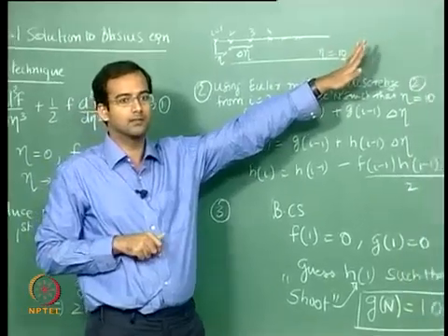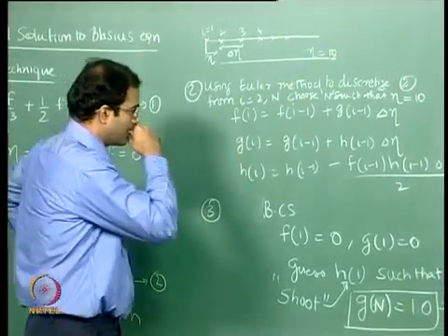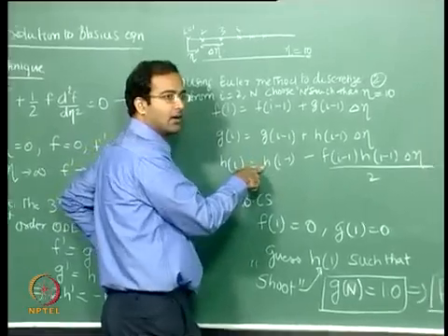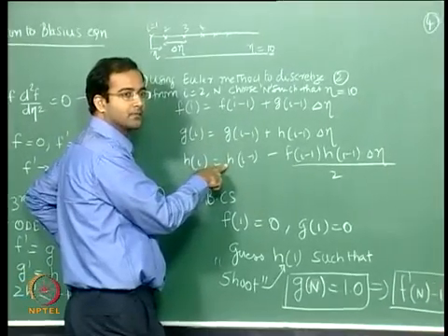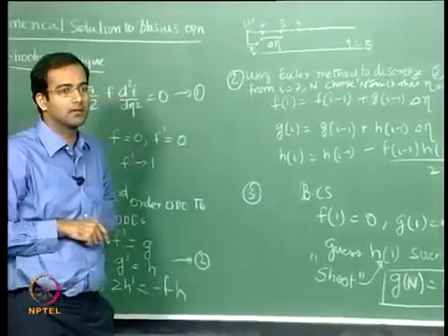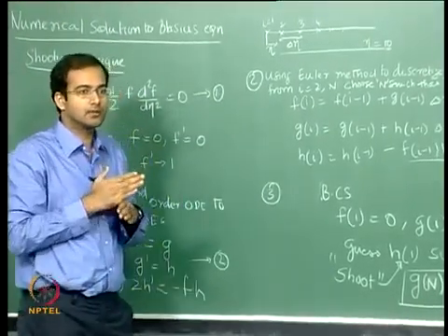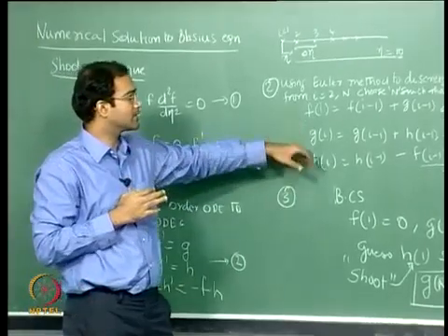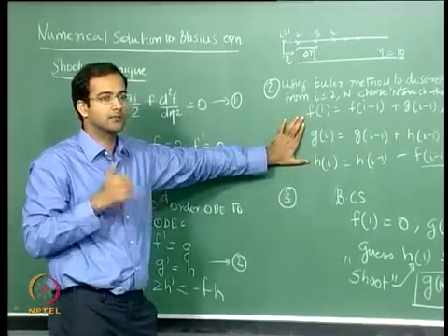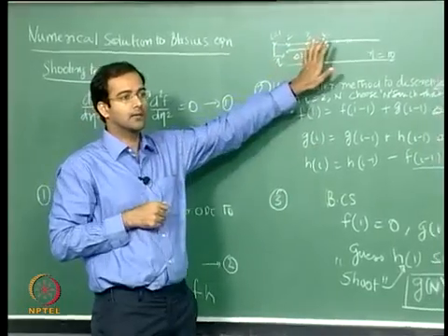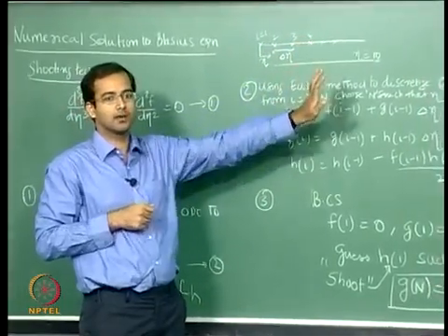Now for this you need boundary conditions for f, g and h all at i equal to 1, which corresponds to eta equal to 0. You need all 3 values at eta equal to 0 to start this marching process, and you have to solve them together. First for the second point you solve all 3, move to the third point, use that value, and so forth.